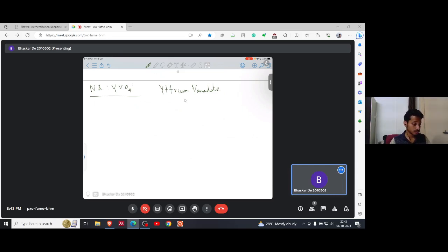It operates at the same wavelength as Nd:YAG but has several advantages over Nd:YAG. These include a 5 times larger stimulated emission cross section and hence higher gain, as well as a 4 times stronger absorption cross section, and a 6 times wider pump absorption band centered at 809 nanometer.